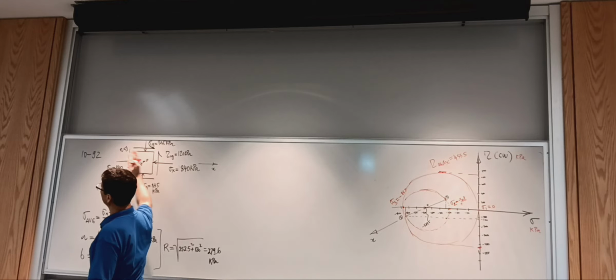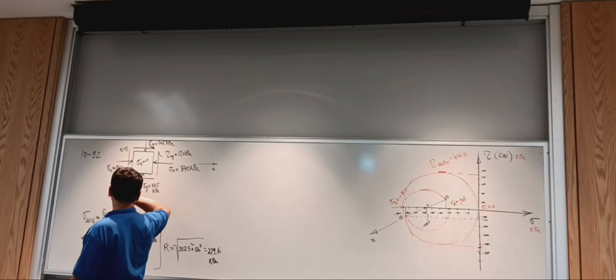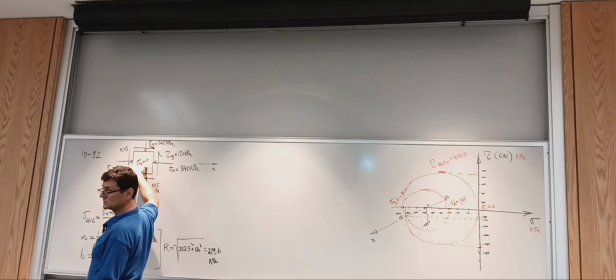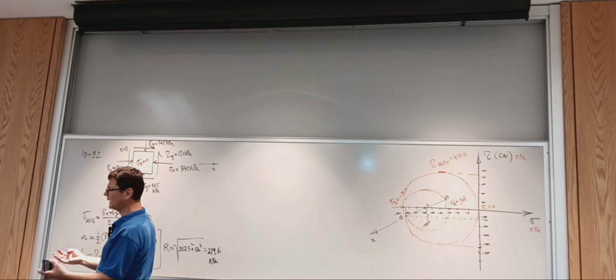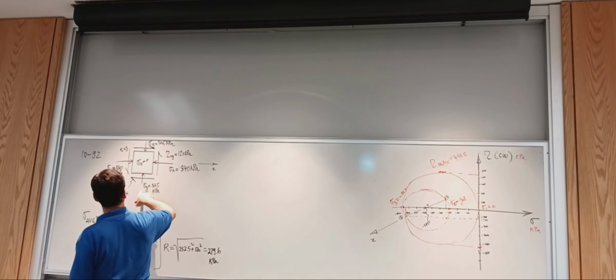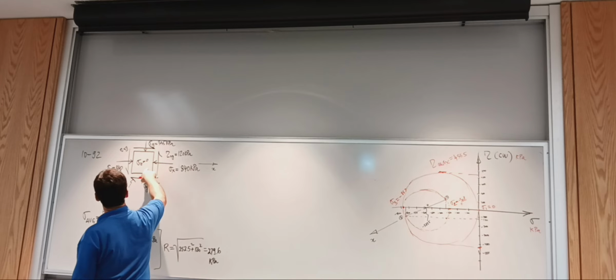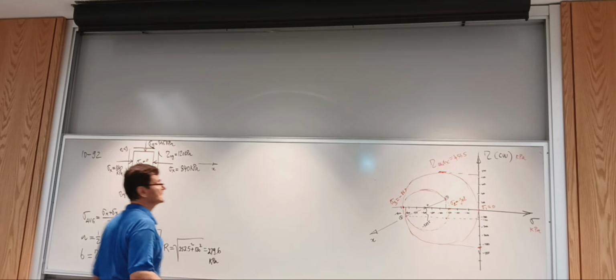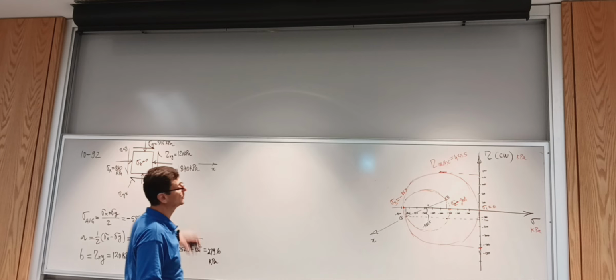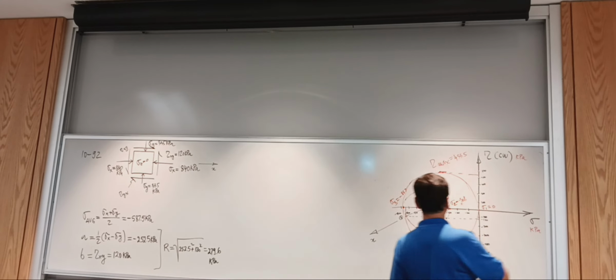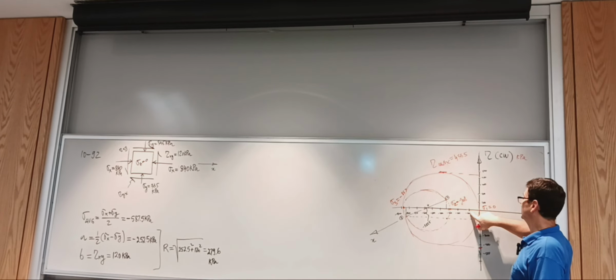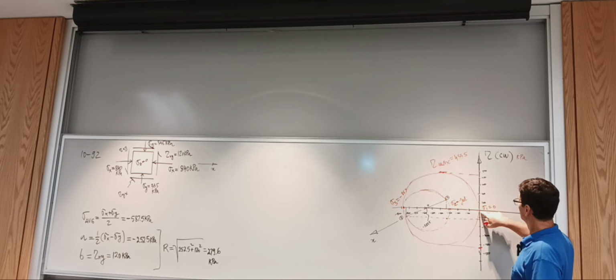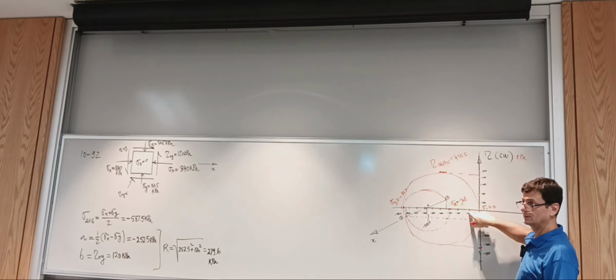You can induce a tensile stress maybe, but the easiest is just to imagine this being on the inside of a pipe, although how do you reconcile the compressive stresses? So if this is instead of being zero normal stress, say negative 100 kilopascals, sigma 1 will shift here.